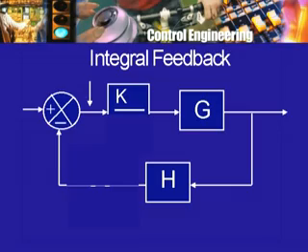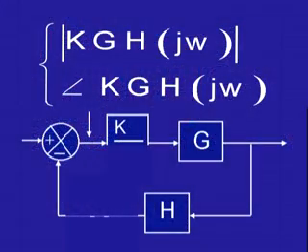In practical terms also, this means something. For example, think of our motor control example. What you are going to do is apply a sinusoidal input voltage to the amplifier, which then results in an amplified voltage which is applied to the motor. The motor will run, and the motor shaft has the tacho generator on it. So, the tacho generator will also produce an output.